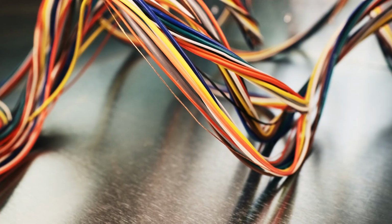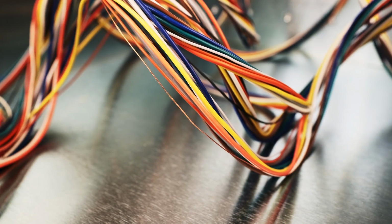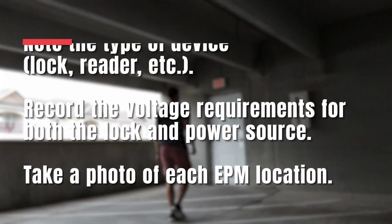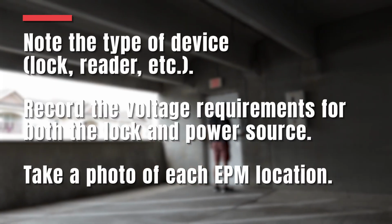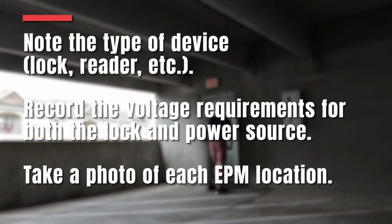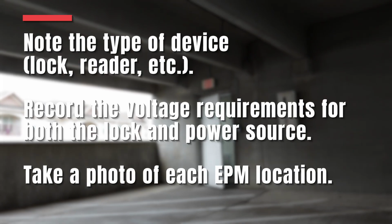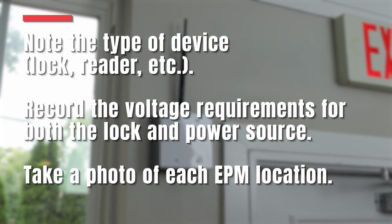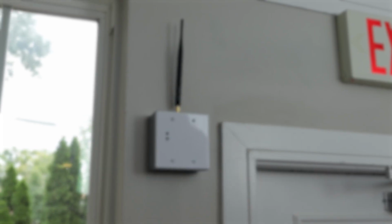With your installer, decide what wire gauge you would recommend for this distance back to that power source. Note the type of device, lock, reader, etc. Consult the installer and then record the voltage requirements for both the lock and power source. Take a photo of each EPM location and upload it to the checklist.